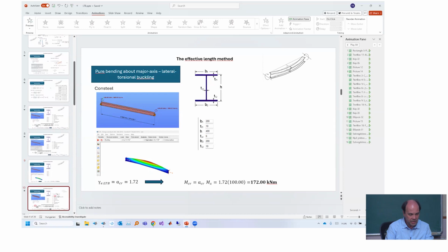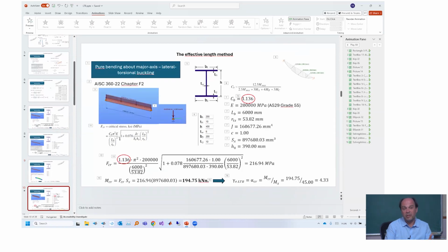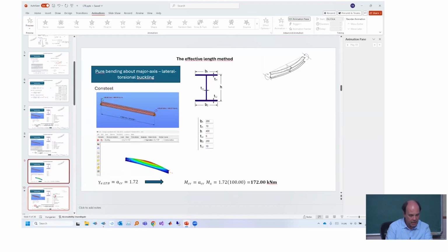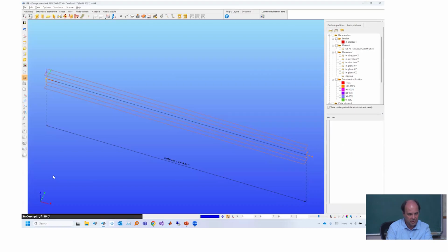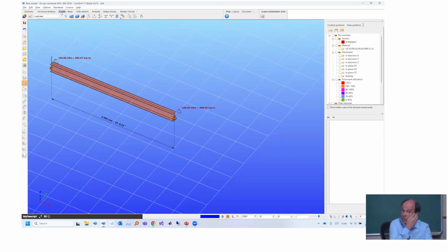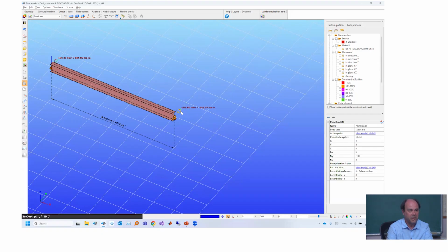Okay, so in the very first step, the most typical situation is a uniform load on the structure. So go back to our model and change the loads. We cannot delete the bending moments, so you can try to click on the load. If you are lucky enough to click on it, it will be selected. Be careful to see that only the load is selected and nothing else.